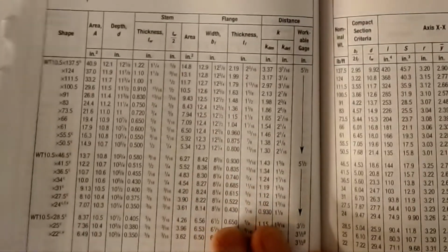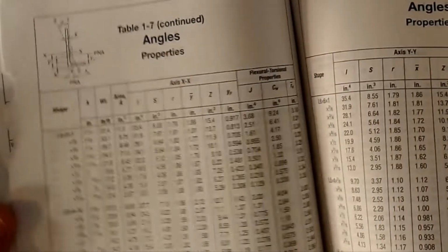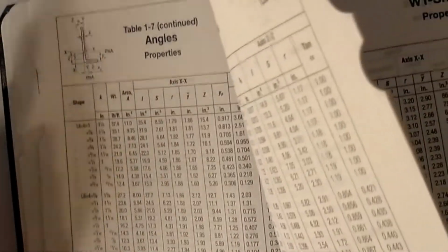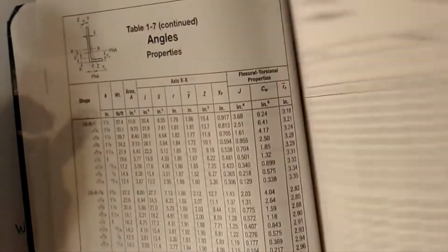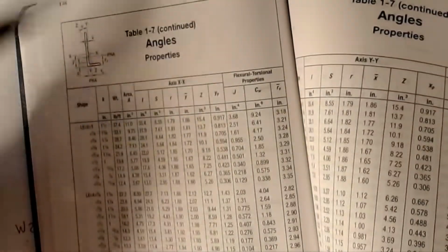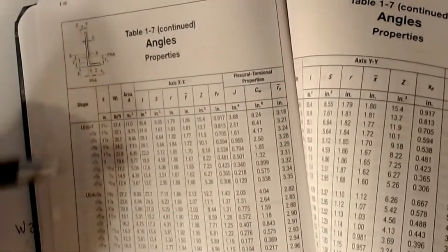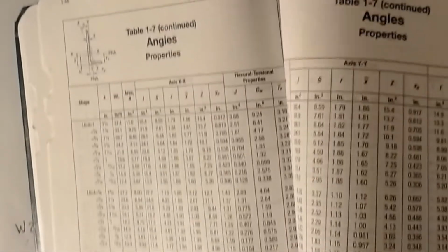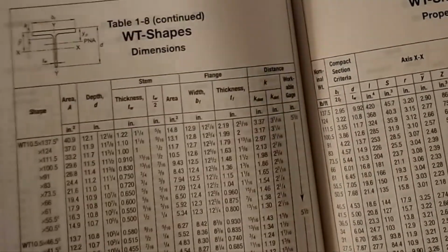Put in tabs for certain cases, particularly the angles. The angles are very commonly used. W shapes you can find pretty easy because they're at the front, but angles are only a couple of pages. The channels are only a couple of pages, so maybe you put an index tab on it to be able to flip to it, depending on what your needs are at the time. Back in the day when I used to work in a consulting office, I actually had the common angles table taped to the wall beside me because that way I didn't have to flip the book open. But those are all just tricks for whatever it is that you're trying to do.